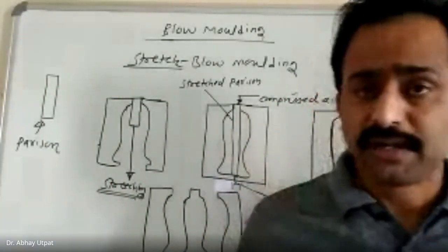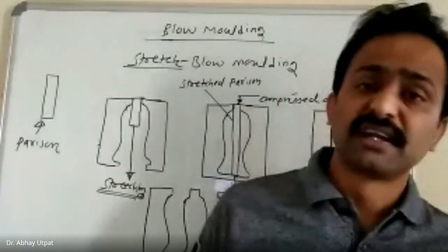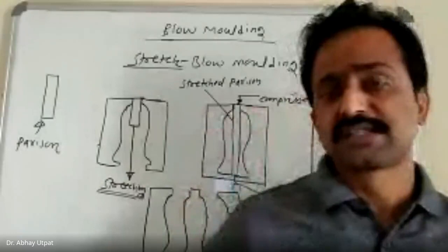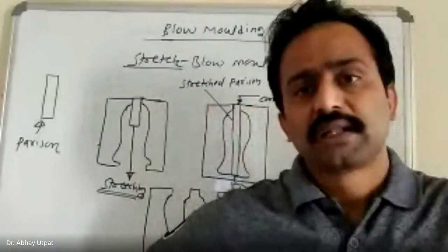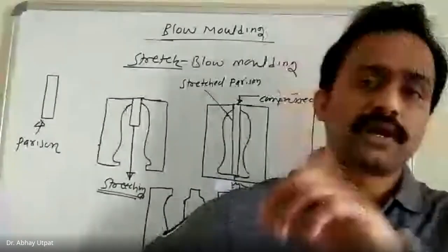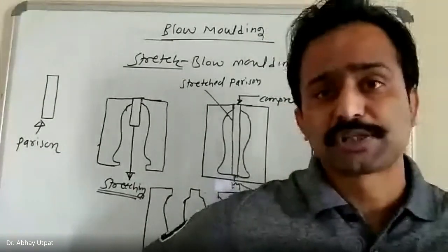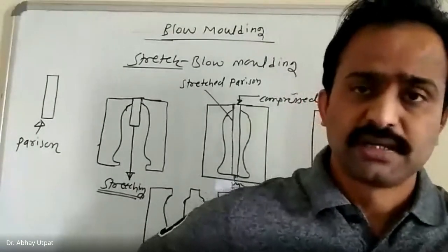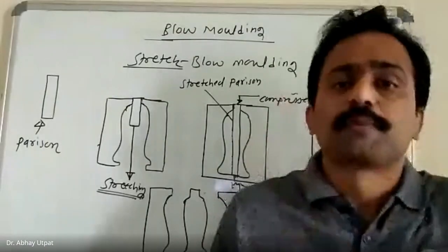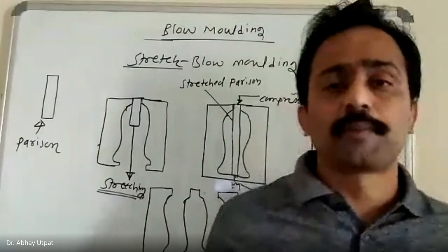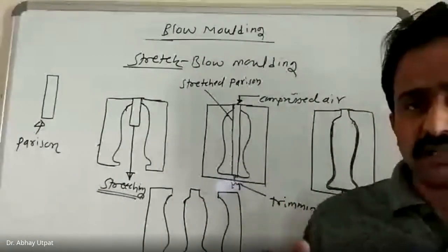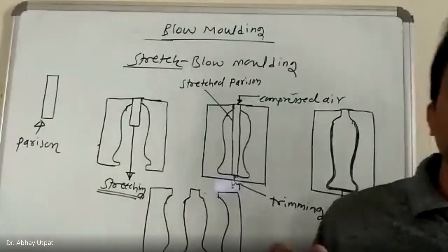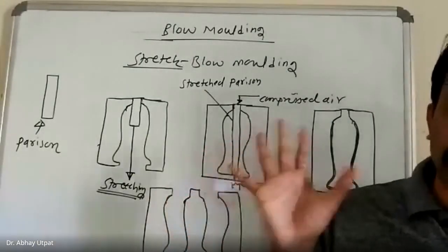What is the advantage of injection blow molding? The intricate shapes at the neck, design, thickness, and accuracy will be higher than extrusion blow molding. You have freedom to design any of the neck shape, threadings, and other parts. And then the remaining bottom part will be blown with the help of hot compressed air by the same blowing mechanism in blow molding process. Now there are certain plastics which are usually difficult to blow only.